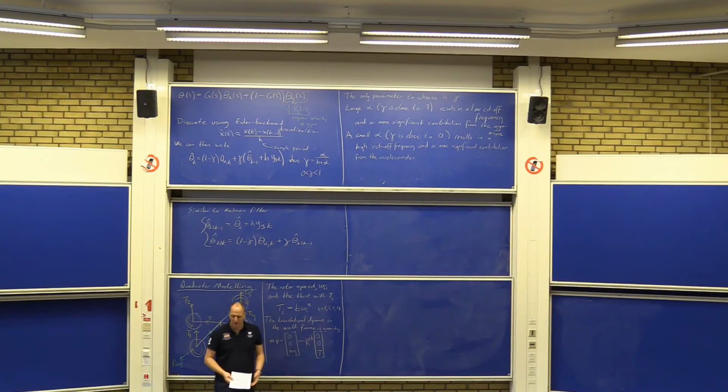So now this will lift in the z direction of the quadrotor, right? So now we need to translate that backward to the world frame. That we do by going through this rotation matrix from body to the world frame.